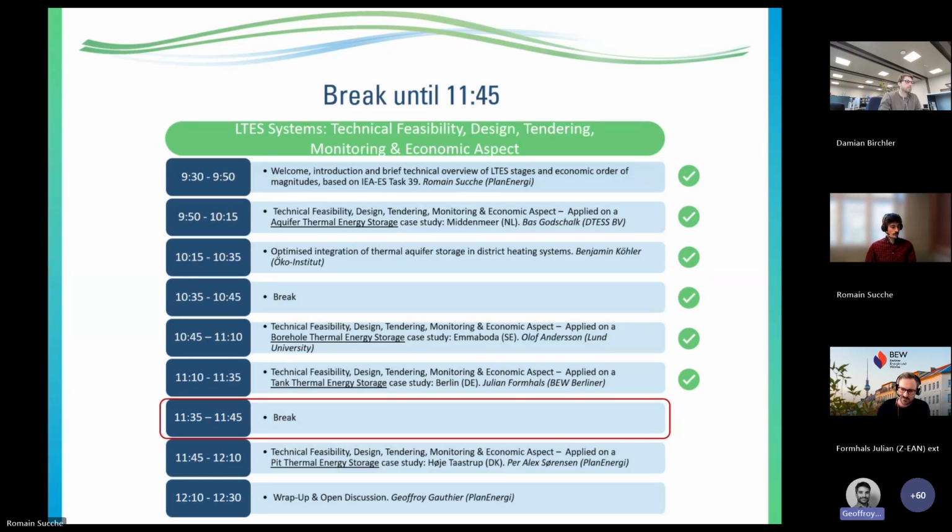Yeah, thank you. If I may add, just for the steel tank construction, there is a norm that defines the construction of such steel tanks, and there are tests that are required for the weldings that make sure that there will be no leakages. So that's how it's done. And then the insulation is some, let's say, regular building insulation. It can be glass wool, or rock wool, or you name it, depending on the level of insulation that is required.